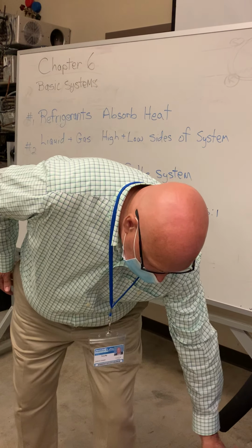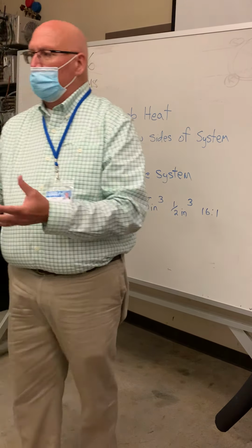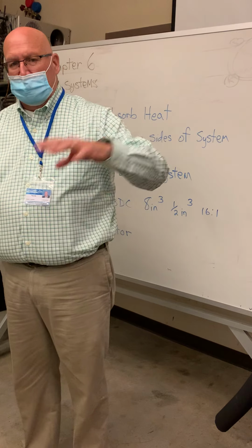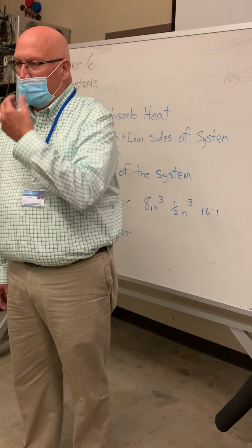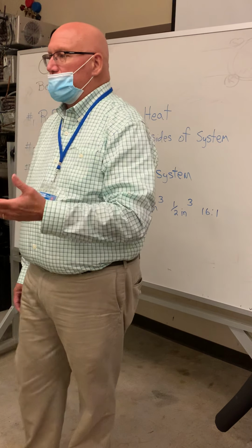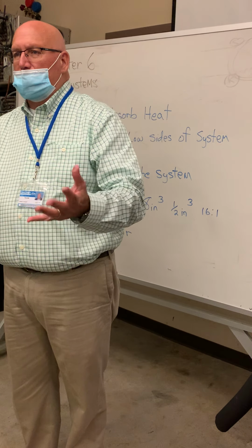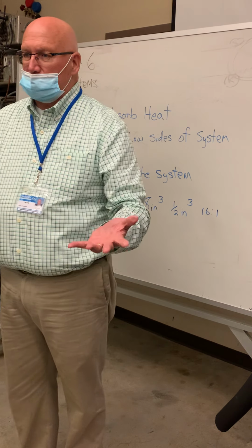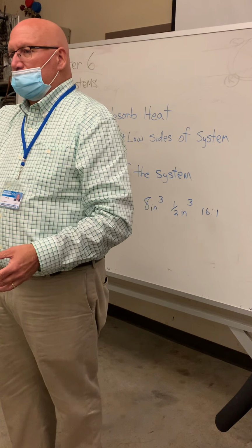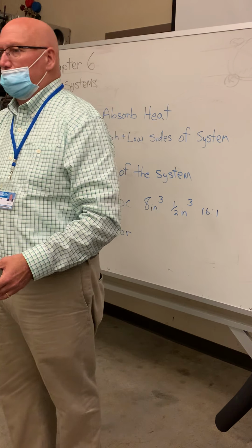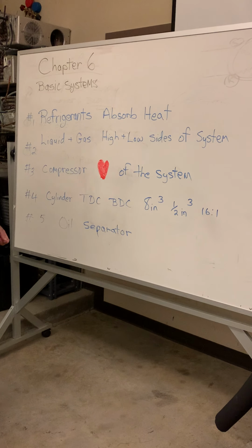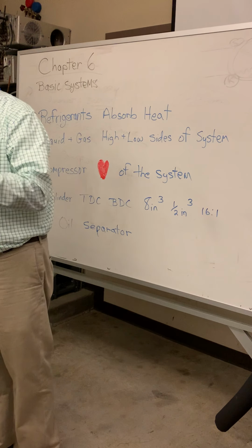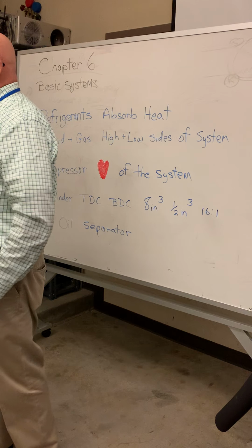So when I say things are warmer or cooler, those are relative terms to what the temperature is either in this space, which we would call the space that we want to condition. That means to remove the heat from, or perhaps add heat to, depending on the season, right? Winter versus summer. Versus outside, which we call the ambient air temperature. So the compressor does that for us. The compressor raises that temperature so that we can take that refrigerant and move it to the outside.